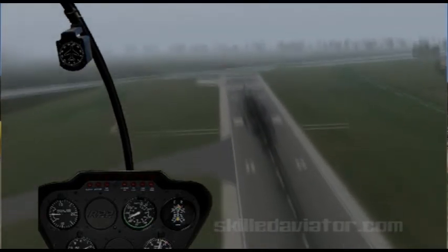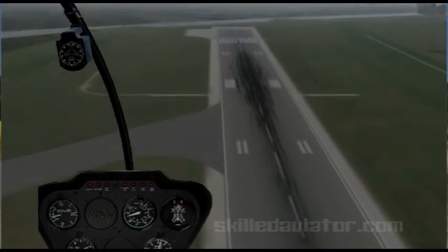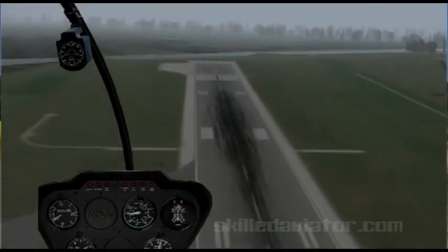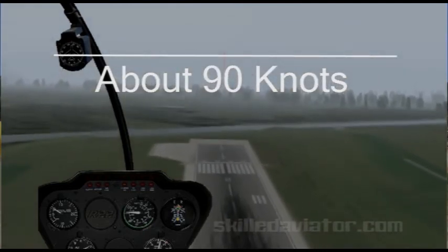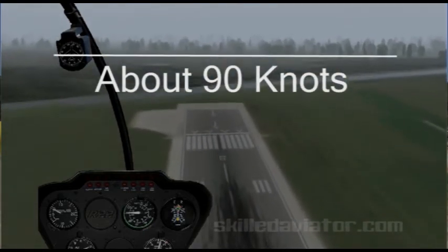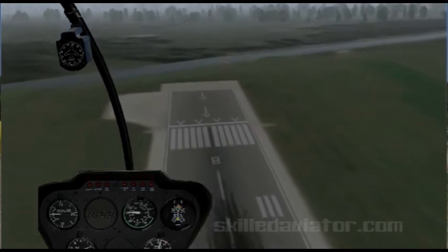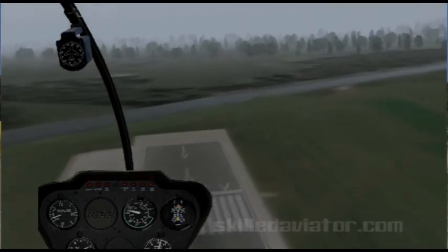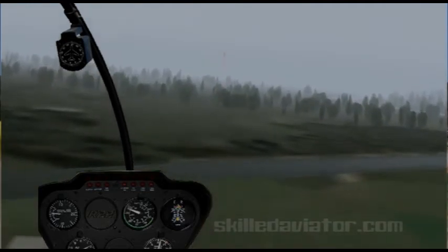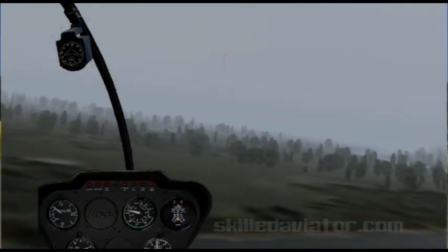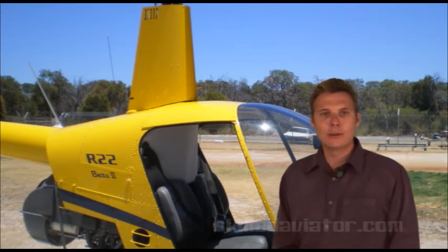If you increase the speed to 90 knots, you will have to push the cyclic forward, the nose of the helicopter will drop and the horizon will rise. Pick another spot on the windscreen to mark this. Now you should be able to roughly gauge your speed by looking at the horizon and the windscreen. Now if the instructor takes you down to do some hovering, see how well you can maintain stability. It's very easy to lose control.